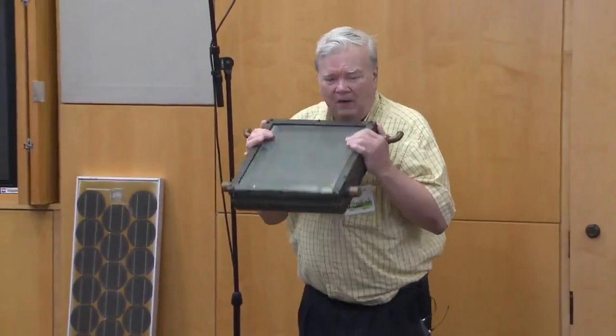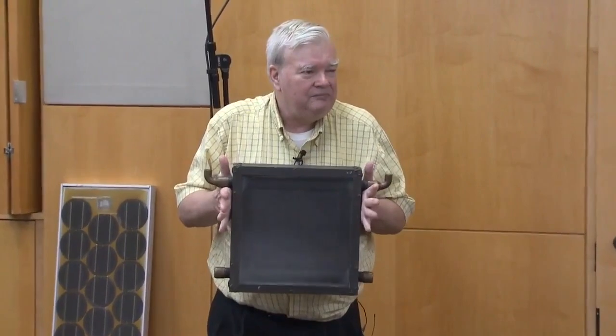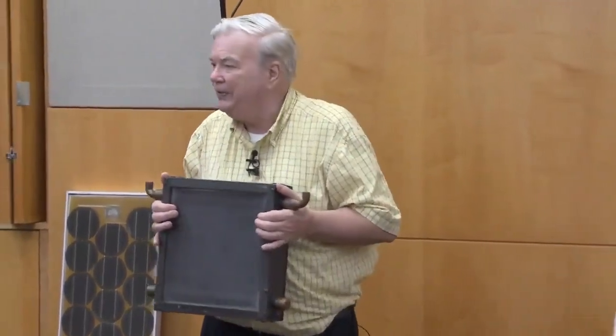All right, this is a solar hot water collector. These are about 4 feet by 10 feet in real life. 2 of these will take care of a household if they're facing south. We get 100 gallons of hot water a day at 160 degrees. So she says, that's hot. I've got an anti-scald valve on it, so it stretches that 100 gallons into a lot more. The hot water comes in at 160. We've got city water coming in, it's adjustable, and it comes out at about 125. So all of a sudden, my 160 degree water blended together becomes not 100 gallons, but probably more like 140 gallons at 125.